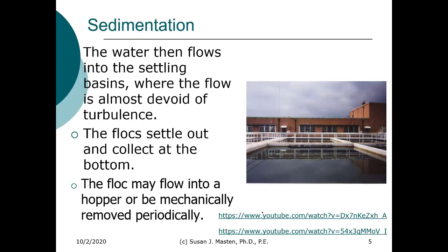So we want to allow the flocs or the precipitated sludge, calcium carbonate or magnesium hydroxide, to collect and settle at the bottom. And then the floc may flow into a hopper and then be mechanically or pumped, physically removed from the system. I've got a couple of YouTube videos. We'll actually look at those later on in the semester, in the unit.